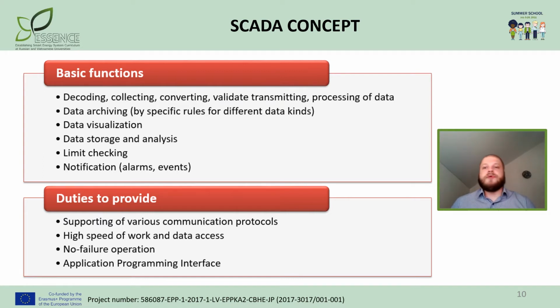Early SCADA networks communicated over radio, modem, or dedicated serial lines. Today, the trend is to put SCADA data on Ethernet and IP. For security reasons, SCADA data should be kept enclosed within the framework of local or wide area networks, without exposing sensitive data to the open internet.